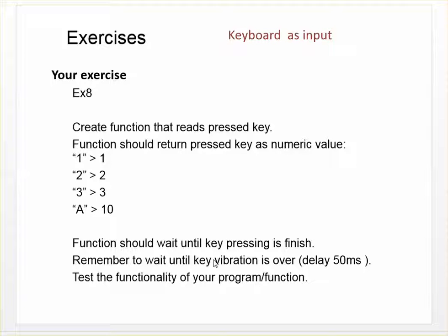And probably you don't know, but in these kinds of keyboards there is so-called key vibration. It means that if the software is very fast, it could detect the key vibration if the software is too quick. The key vibration means that the status of the read key is vibrating for a short period from 1 to 0, 0 to 1. So you have to wait, let's say 15 milliseconds, before you know that the key vibration is done.